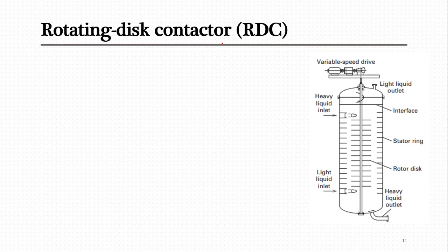Okay, we have seen in the last lecture the mixer and settler column, and when I was showing you the mixer, we saw the rotating disc contactor. A rotating disc contactor consists of rotating discs throughout the column, on a rotating shaft. It doesn't contain any packing, any plate or such thing. They are the simplest ones, which we saw yesterday.